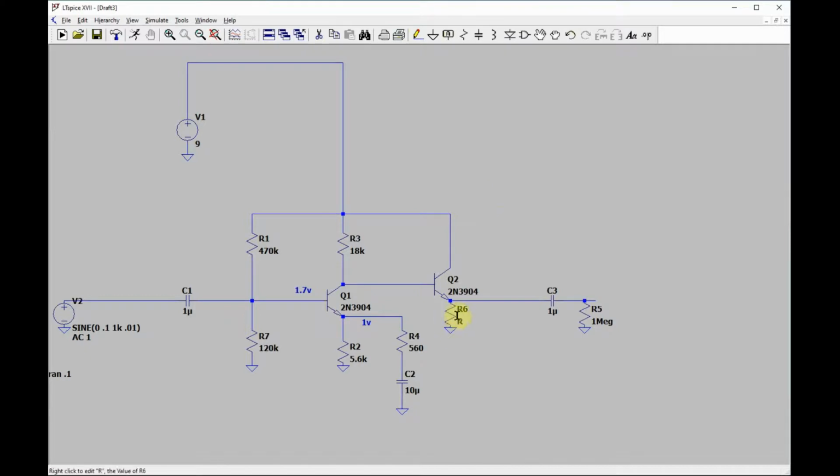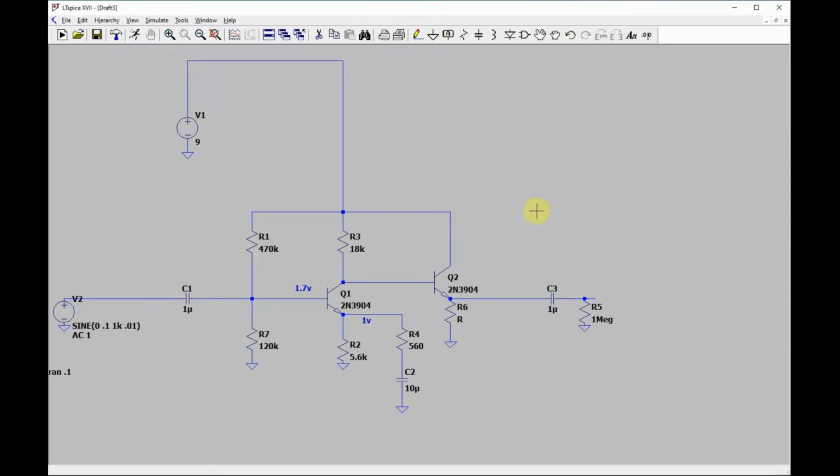Now, we've got an output coming to this base, and that signal gets copied right across there. And this is low impedance now, way lower, and it's 0.7 volts lower. I never marked what this is, but whatever this bias is here, it'll be 0.7 lower, thereabouts. So you can do this. You just add these 2 parts to your circuit and you're set. I mean, you can run this into the next stage.